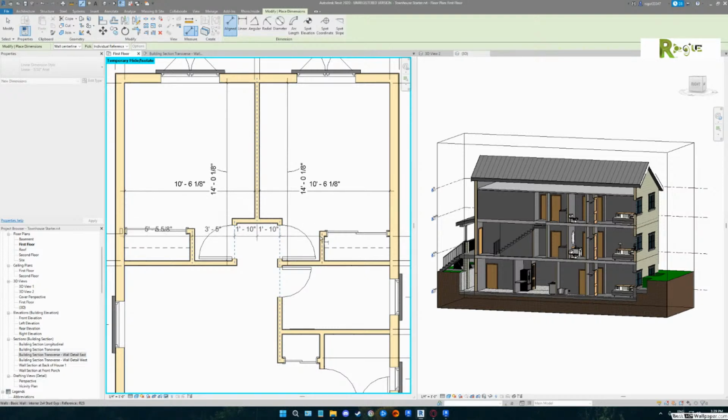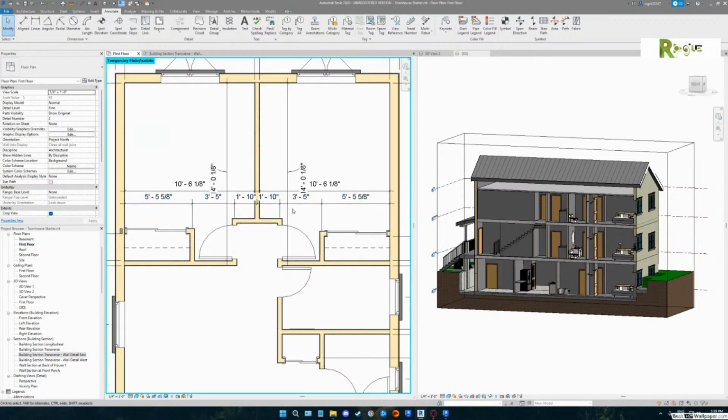What I'm trying to show you is that this dimension string now lets you look across your drawing and say, did I miss any walls? You see all the blue dotted lines it's creating for you? So it's showing you all the walls you did pick up. I see. And then that last wall on the edge, if you wanted to get the wall face, you could go there with it saying wall center lines and do a tab. And then it would let you pick it. And then it would let you be continuous. That makes sense? So that's a better way to do it then.